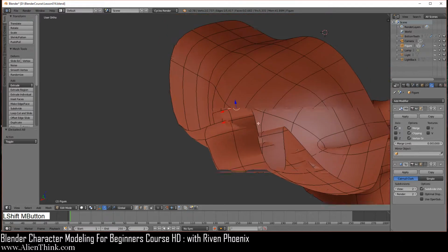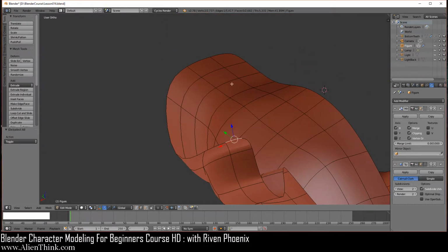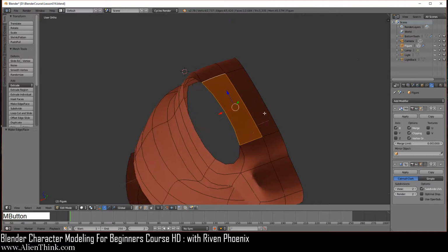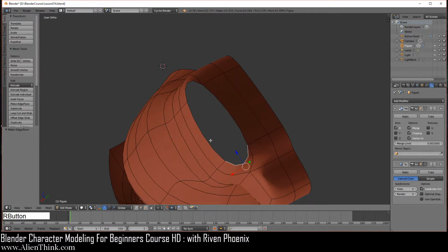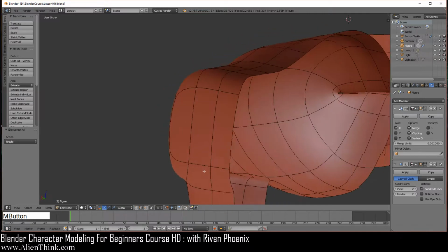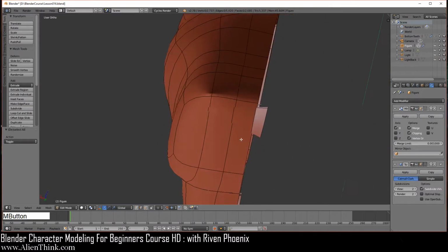So I have this edge selected. Actually, it's better to look at it from this angle. Click on this edge and press the F key to create a face. Click on this edge. Click on this edge. Press the F key to create a face over here. Okay, and then if you look at this, is 1, 2, 3 over here. So if you just Alt and click it, do F, it'll just select it this way over here, like so.